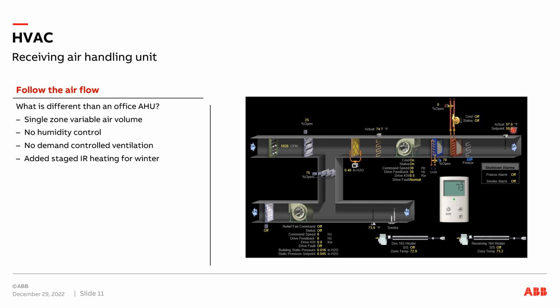There's no demand controlled ventilation here, so I don't really care about the CO2 level coming back in because I'm just going to be bringing in a lot of air into here, keep positive pressure.